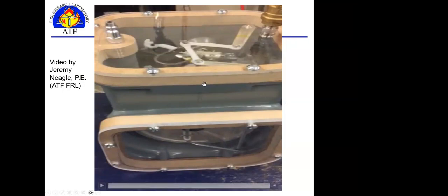If you look closely, you'll see that basically this outlet side here is connected to this pipe. There's a little bit of a pipe underneath here. So your gas comes in on this side, and it goes in through these sliding valves. Work goes through the bellows, through a series of vents and channels, and then comes up this side. And that rotating here up top is what's getting your meter to spin and actually calculate or record how much gas is being used in that structure.